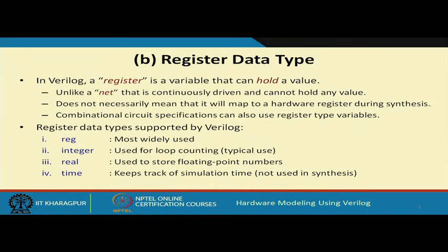Now, let me just emphasize one thing here, that we shall be talking about many features of Verilog which are simulation only features, that make sense only when you are doing simulation. When you are carrying out synthesis, those features do not mean anything, and the synthesis tool will simply ignore them. Let me take some examples. Whenever we instantiate a gate, we had seen some examples where you have specified some delays of these gates, right.